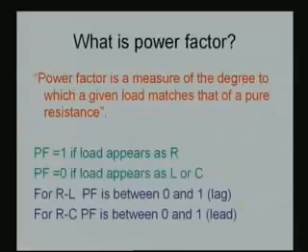So, we come back to our basic question, what is power factor? Let us now give a notional definition, and later on, when we use the mathematical relations, we can have a mathematical definition. The notional definition will in fact help you derive the mathematical relationship. So, power factor is a measure of the degree to which any given load matches a pure resistance. That is our notional definition.